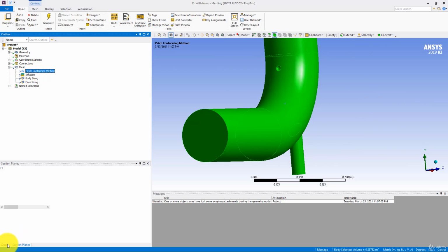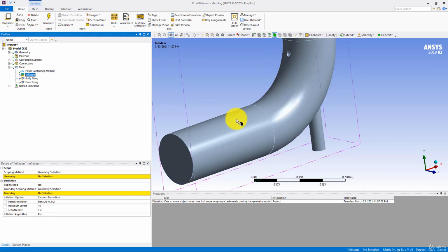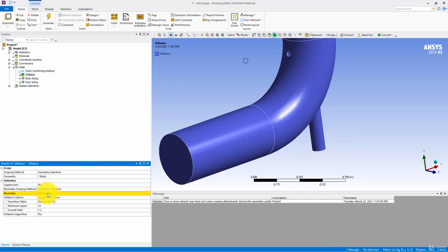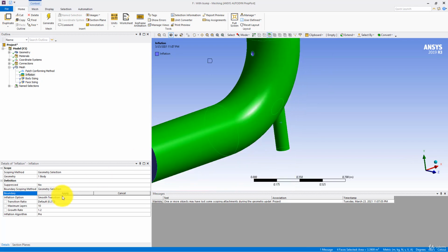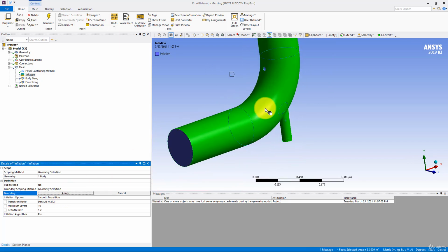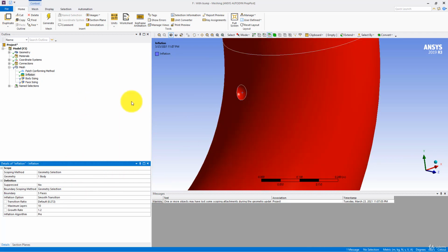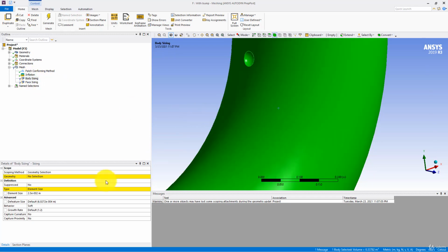Okay, so as usual, you can see some errors in the meshing. So simply choose the same commands and apply them on the geometry. So there is not much difference here. So this is the main geometry, which is the body, and choose these four faces for the inflation, and also the bump here should be selected.